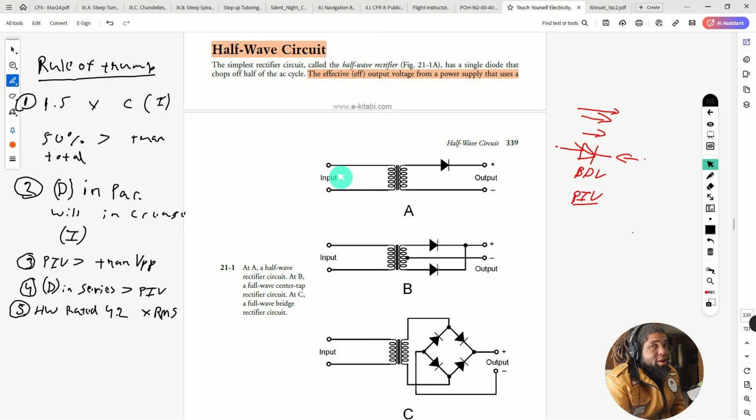at least in North America, most of the time the frequency of your voltage is 60 hertz. When you use a full wave rectifier, which we're going to see later on, not a half wave, with a center tap transformer, you're using both halves of that transformer and they're basically being combined. Your frequency is going to be 120 hertz.